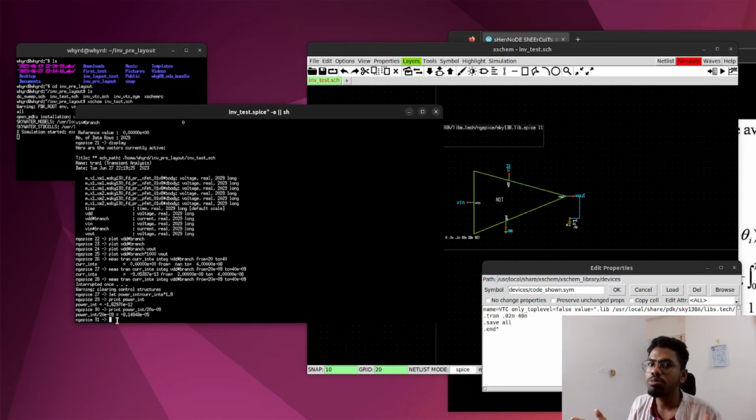So now, how to reduce your power, because reducing the power is the main concern here. One is to reduce your CL, and we know CL is the load capacitance, which depends directly or indirectly on the layout of your inverter and the load, because this load capacitance is coming from the next layout or next device.